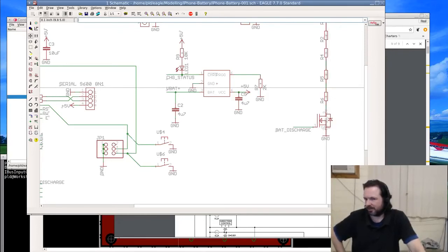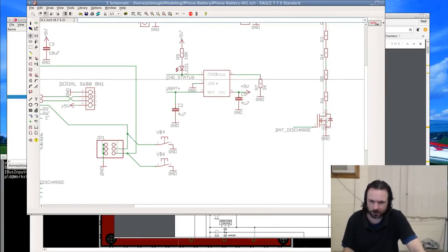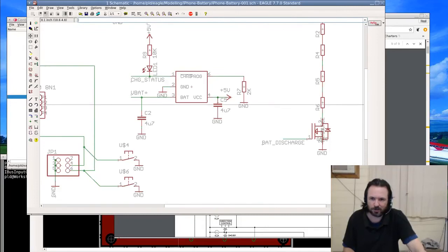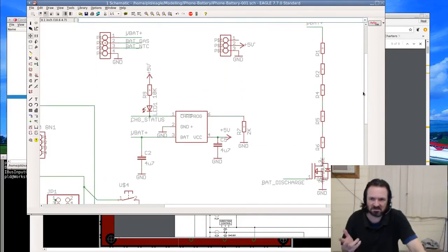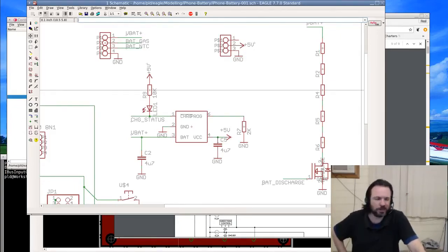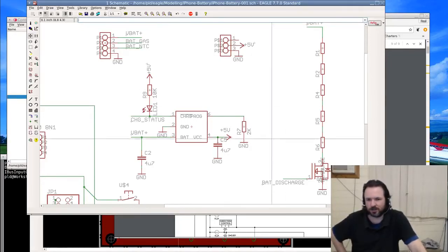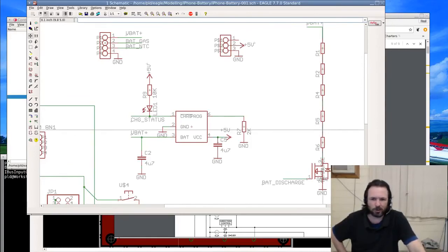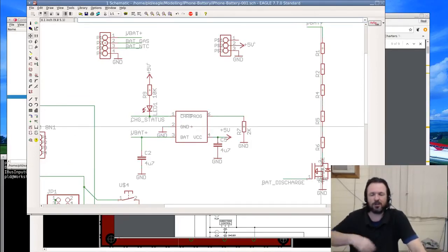I'm trying to see what's within the range of the ADC to still give me some decent resolution. So we've got 10-bit, and if I'm assuming these are about, say, 1 ohm, why not? 500 milliamps, so we'll have half a volt going across them. So yeah, that gives me 9 bits of resolution, half a volt on the 1.1 volt range. So I could do that.